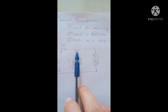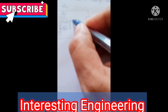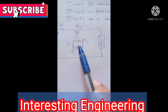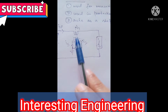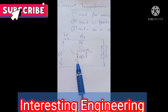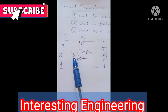Here we have two windings, primary winding and secondary winding. The number of turns in the primary winding is denoted by N1 and the number of turns in the secondary winding is denoted by N2, and here we have a single turn on the primary side and many turns on the secondary side, and on the secondary side we connect an ammeter for measuring the current through this instrument current transformer. This current transformer should always be earthed so that it provides safety to the personnel operating with this instrument. Current through the primary is denoted by IP and current through the secondary is denoted by IS.